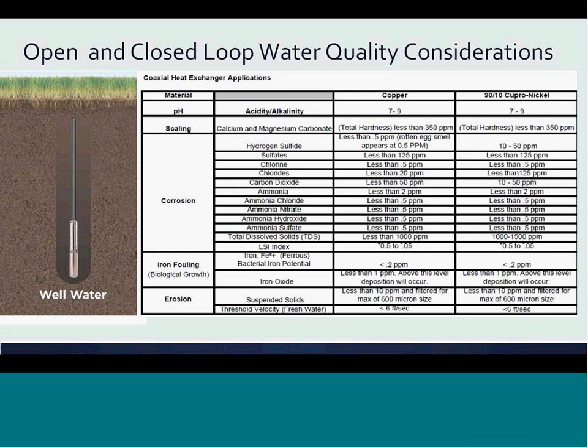Water quality is something that has only recently started getting more attention in the geoheat pump industry. In systems installed in warmer regions, only local tap water is typically used to fill the closed-loop system. The point is that the quality of water can vary significantly, and the use of various pipe materials above ground in the building may require some type of water treatment for the circulating ground loop water. It is important to be aware of the equipment manufacturer's water quality requirements, such as those depicted here, and also of the local groundwater regulations.